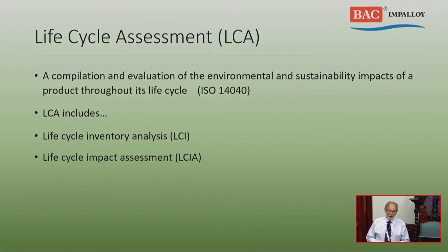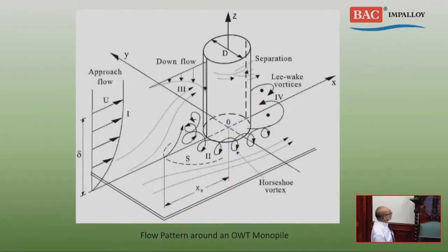And there is then another factor, particularly for inshore waters, and that is water velocity. If we look at the amount of turbulence that you get around a monopile, for example, there are many factors which affect the water velocity. Water velocity varies with depth as the water approaches the monopile.